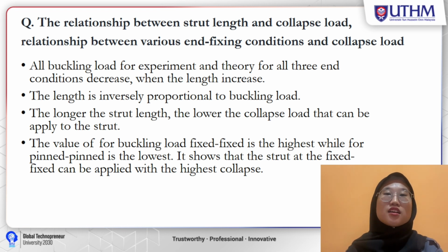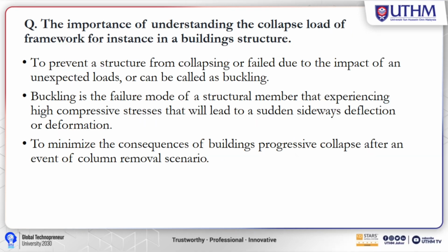Besides, from the observation, we can also see that the value for the buckling load of fixed is the highest, while for the pin experiment is the lowest. So it shows that the strut at the fixed condition, fixed end, can be applied with the highest collapse load.